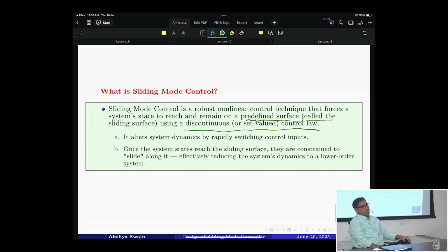This is exactly the sliding mode controller. He knows because this is the sliding surface. So you have to push it by a control law here. Right? Not only that, you see how it becomes robust. Mathematically, we can prove it. Once you are here, nothing can happen to you because all protection has been taken care of. If you are outside, then nobody takes care of you.